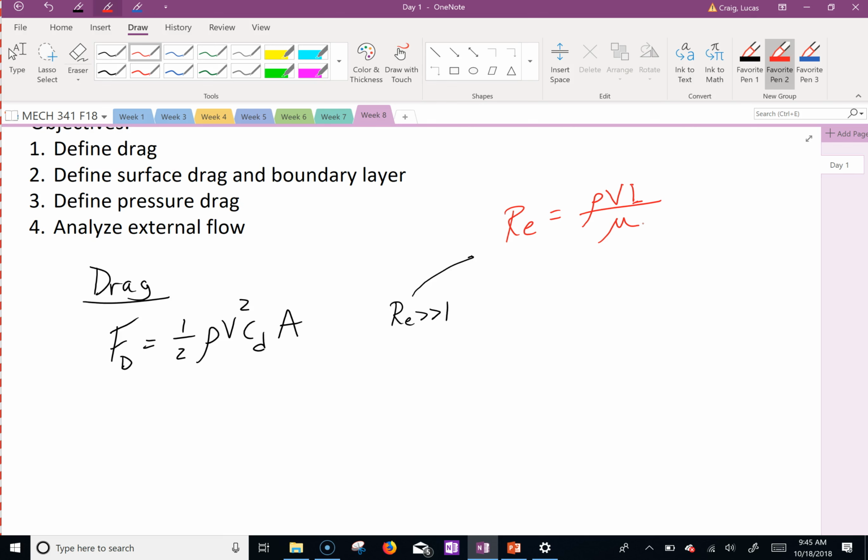So for us, a large Reynolds number has a lot of inertia. We have a lot of mass, and as we move with acceleration, that term is huge compared to the viscous force in air. If we were moving in honey, that equation is no longer valid because the viscous force is now much greater.